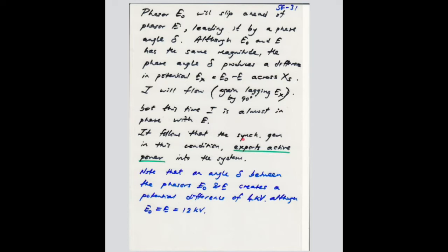In this operation, the machine exports active power into the system, and hence we are fulfilling the main objective of the generation system, where we export active power into the system. Normally we don't operate the generator in the other two modes, because for the consumption of reactive power, we expect the consumers to generate their own reactive power, and it's not being transmitted by the utility.